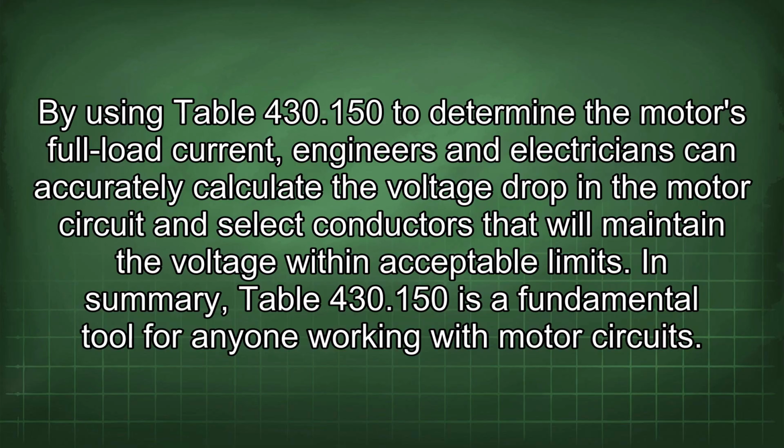By using Table 430.150 to determine the motor's full load current, engineers and electricians can accurately calculate the voltage drop in the motor circuit and select conductors that will maintain the voltage within acceptable limits.